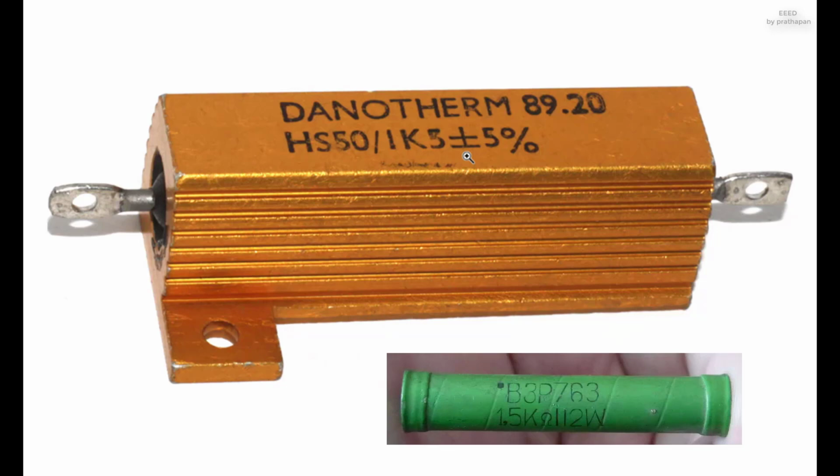In a high voltage circuit, attention must sometimes be paid to the rated maximum working voltage of the resistor. While there is no minimum working voltage for a given resistor, failure to account for a resistor's maximum rating may cause the resistor to incinerate when current is run through it.